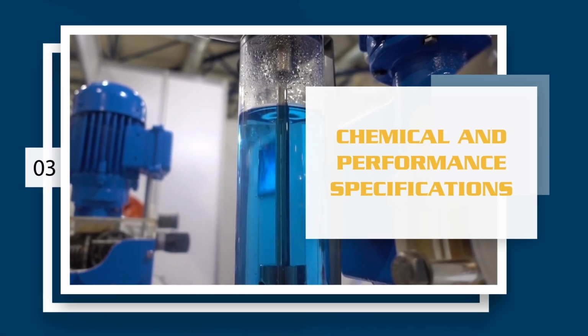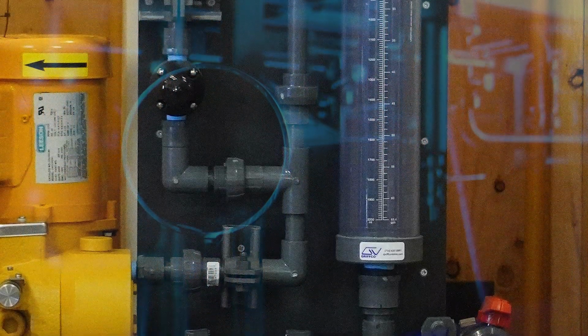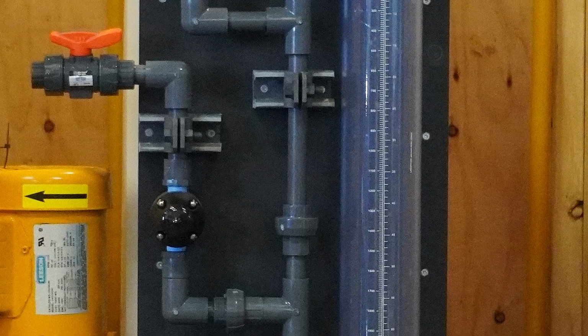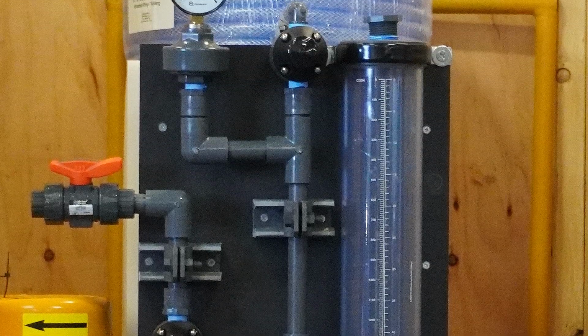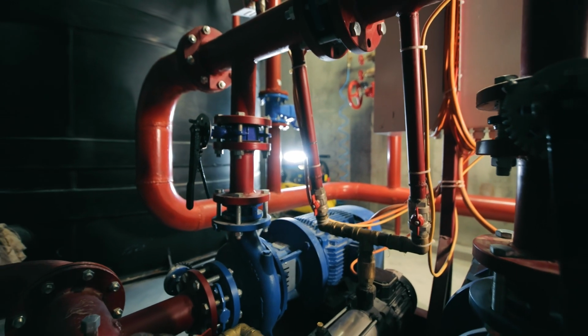Choosing the right materials for the wetted parts of your system isn't just about reliability, it's also a matter of safety. The materials must resist corrosion, as the chemicals could compromise the skid's structure over time. The rate and pressure at which the chemical is injected directly affects process efficiency. The pipe strength, pump power, and motor size should all be tailored to the system's specific performance requirements.